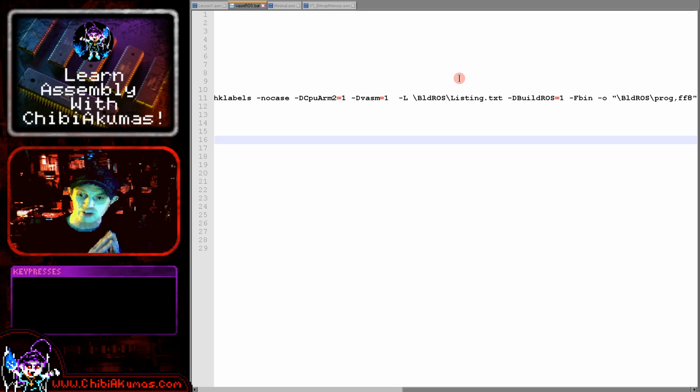It's quite handy if you're having trouble or if you suspect your assembler is making changes behind your back. Some of them do optimization, and in some cases in testing things haven't worked the way I expected because the ARM is almost correcting mistakes that I'm intentionally trying to make. So it's sometimes worth seeing that listing file, but it's not something you would necessarily need as a beginner.